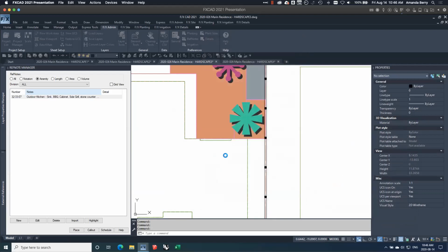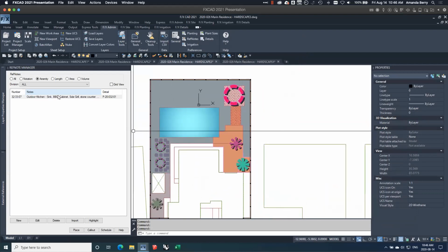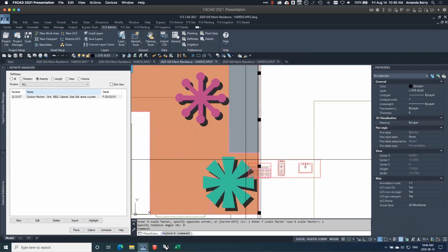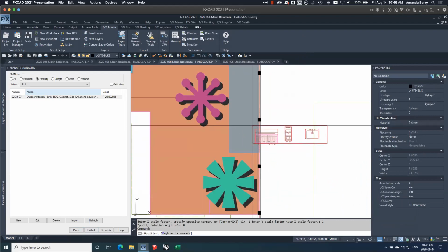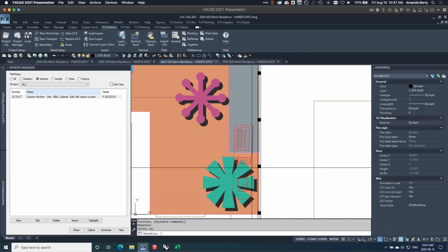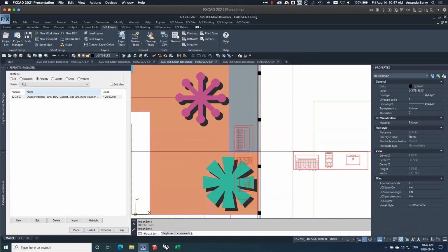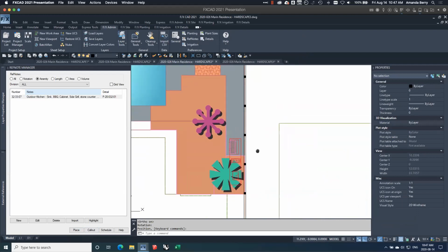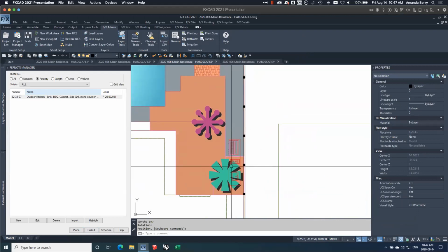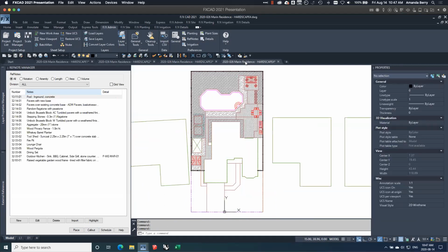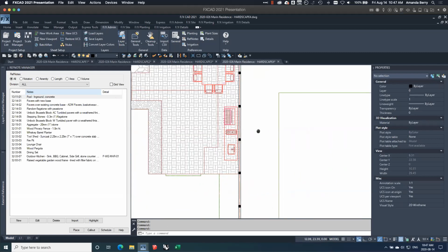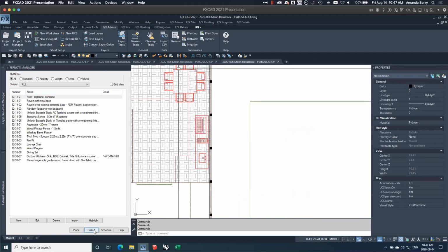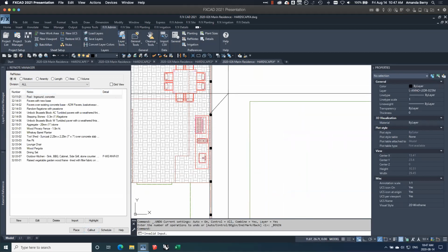But with all of that set up, I can do a lot of really cool things. Like I can place that and just kind of place that in here. It's going to automatically ask me to rotate it. I hit F8 to just get it along there. And I can do things like call that out. I can schedule it. I actually have it in here to show you. So I've placed that in. I can call that out using this callout tool on my reference note plan.